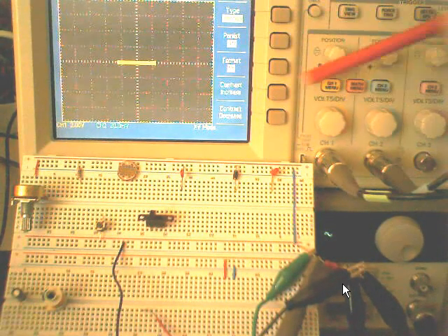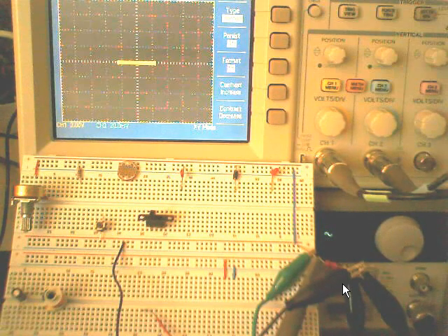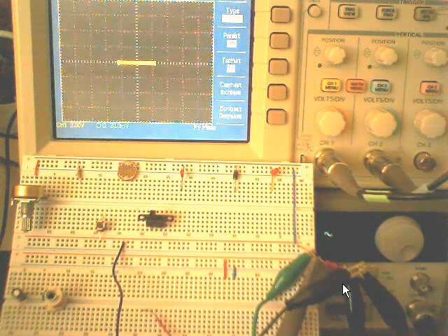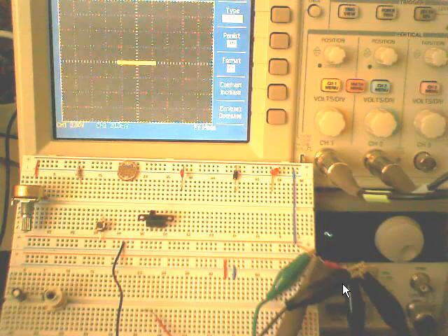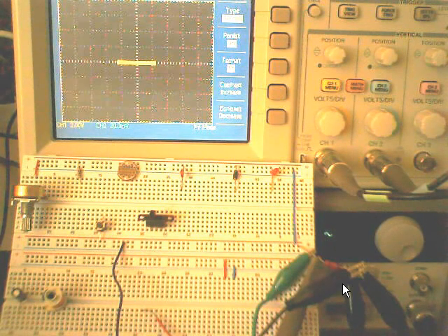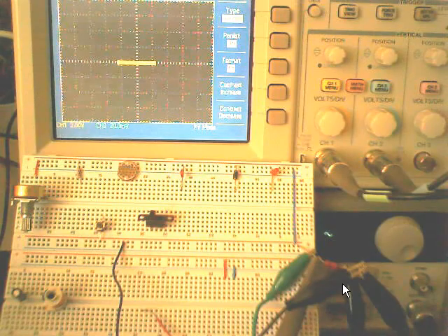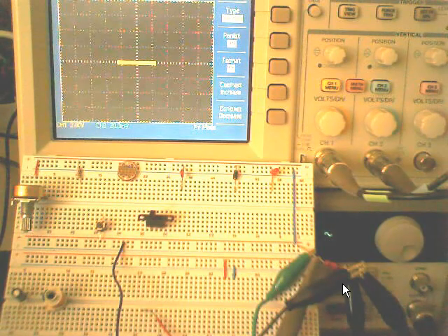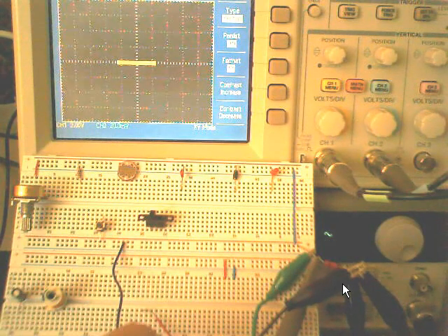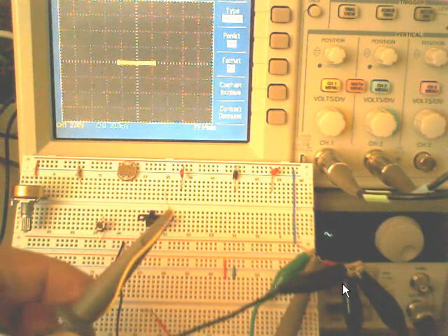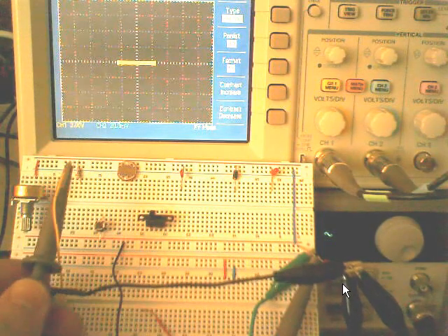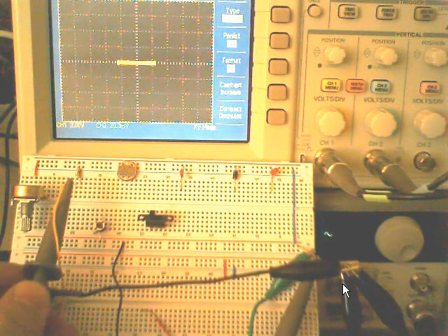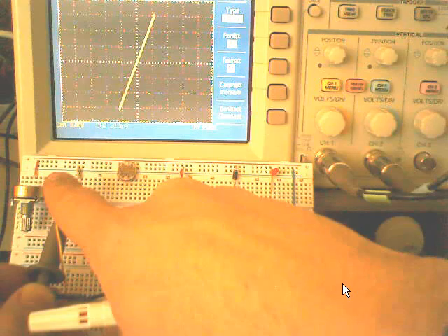This is a device called an oscilloscope. It's mainly used for the VT graphic of components. You can see the voltage with respect to time. But with this purpose, you can use it to show the IV characteristic of components. For this purpose, I will apply some signal on components and show you the IV characteristics of components.